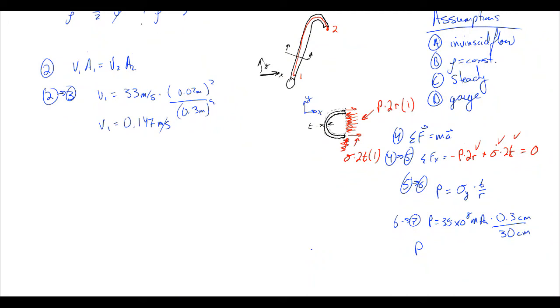You'll note, hopefully, if you're trying to figure out how large pressures are, that's only about 3 atmospheres. So a 30 centimeter diameter tube that is 3 millimeters thick is really only rated to about 3 atmospheres of pressure, which is not much, right? So what could we do to make this pipe hold more pressure? Well, we can decrease the diameter, make this smaller, or increase the thickness. And that's really the only options that we have. Unfortunately, we don't want to do either one.